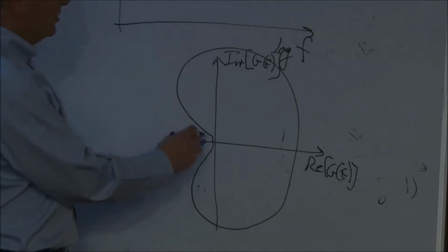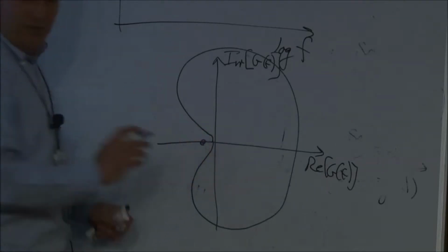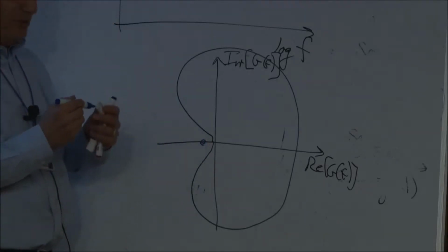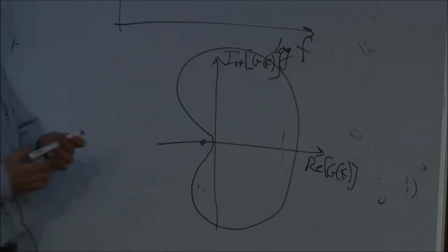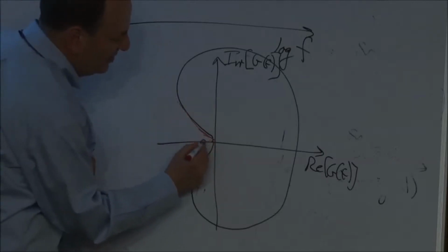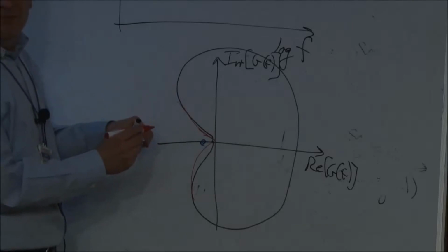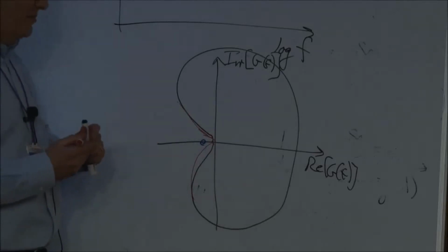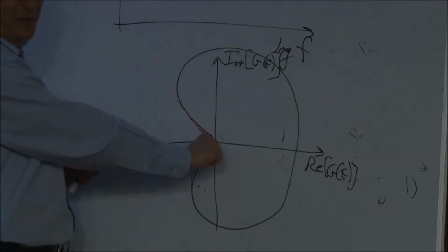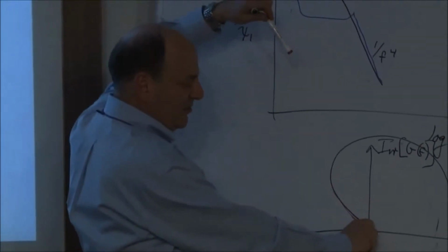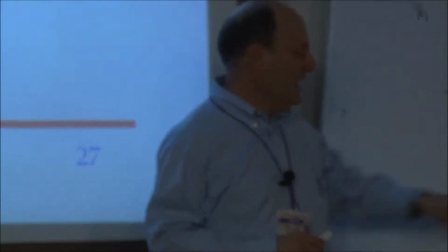And occasionally, you design things like that original version of what I showed that in principle is just barely stable for arbitrary values of overall gain. The naive version of that servo just barely kisses this axis. But what it actually does when you actually build it with real things is it crosses the axis. And as a result, you'd better not turn up the gain. Turning up the gain then means blowing this up. Better not let that crossing of the negative real axis appear at the left-hand side of 1.